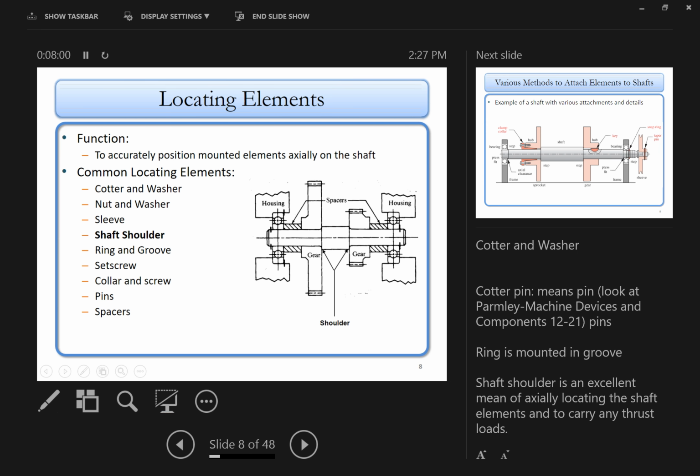So, for example, you put the shaft against the shoulder over here now, but then we also need to prevent the shaft from moving axially, right? You can't let it wobble all the way through this, falling off the shaft. So we can use this thing here, which is called a sleeve or spacer, to put a spacer between the bearing and the shaft, to basically prevent the shaft from going in the axial direction. Okay. And you have the bearing at it here.